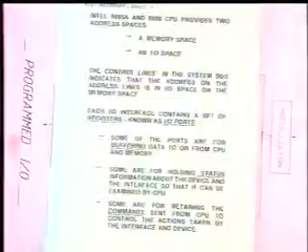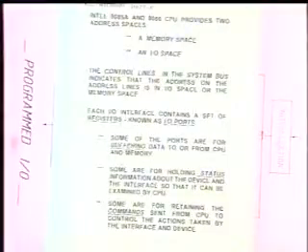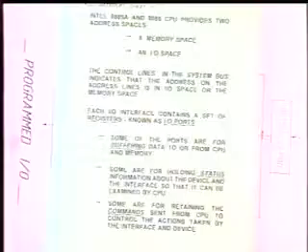So basically, one can say the interface is hardware which consists of certain registers: a data buffer for input as well as output, and a command register, which will hold the command generated by the CPU to decide whether it has to do reading or writing. And then there is the status information, which is very important, because some of the peripherals are normally slower than the CPU, as a result of which there must be status information to say whether the peripheral is ready or not.